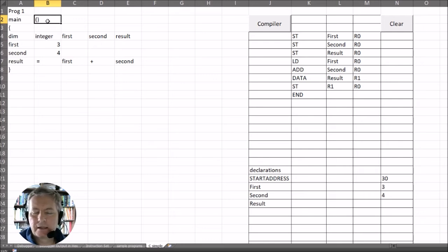Now we would be able to go in and actually run through the code, and at the very end it would save the result into memory, and then it would go back to the stack or somewhere in memory, and pull back out the original values for R0, 1, 2 and 3. So in effect we don't want to overwrite what was already in the registers R0 to R3. That's what the main section would do.